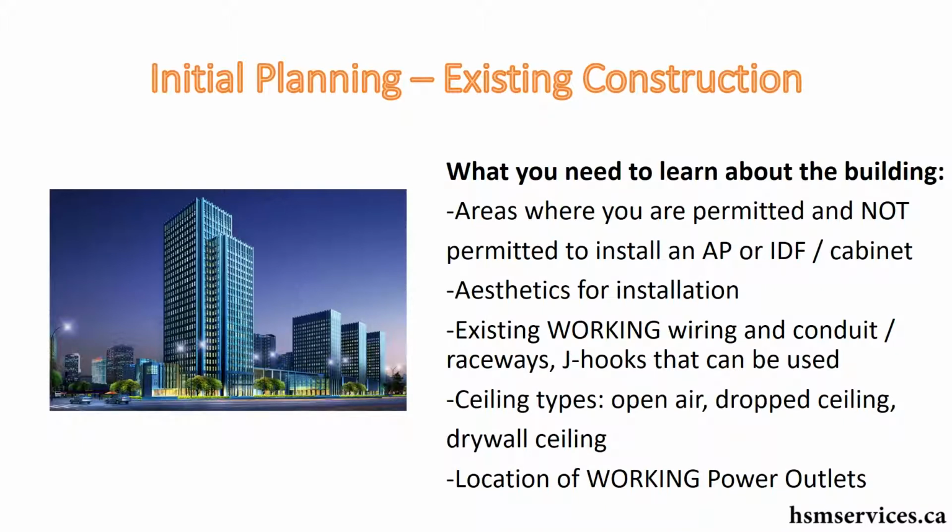You also want to see if there's existing wiring that's actually working, and I have to emphasize that the wiring is actually working. Wiring that already exists could save you a lot of money. It could save your client a lot of money, so that you don't have to run new wire. Same with conduit or raceways or J-hooks, especially in situations where it's impossible to run new wire without getting a Sawzall and cutting through the roof.